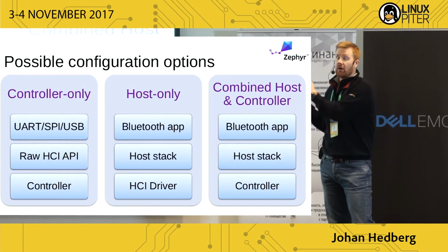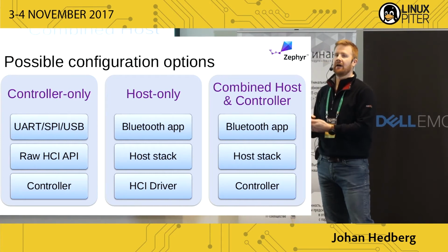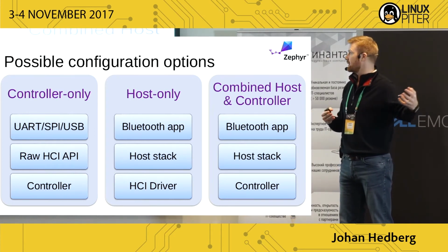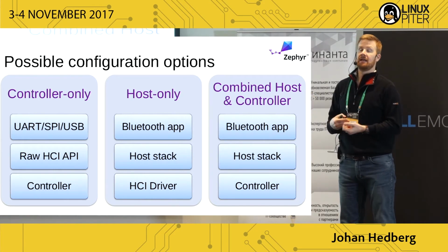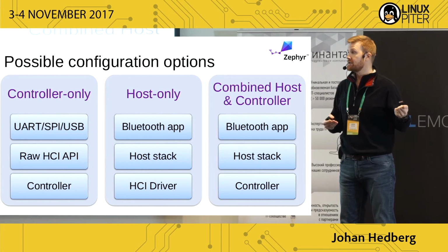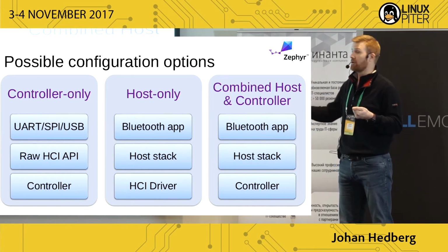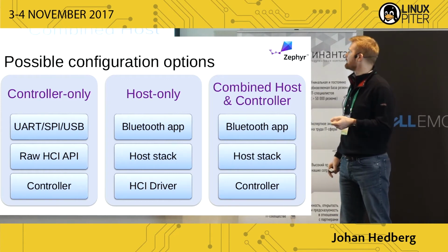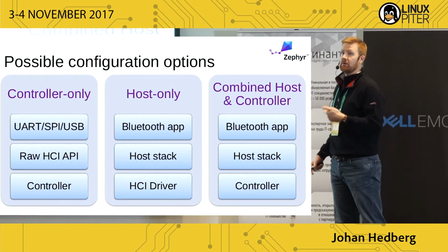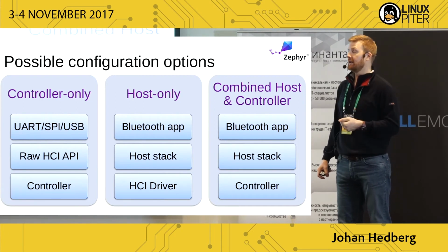The Zephyr Bluetooth stack, you can build only the host, in which case it requires an HCI driver for a physical HCI transport, like UART, for example, and then the controller will sit on another chip. An example of this is the Arduino 101, where you have the Quark running the Zephyr host stack, and then you have an nRF51 running the Zephyr controller, and they talk to each other over UART. And then, as I mentioned earlier, you can have them running in a single chip. So you could do this right now with any Nordic controller, the nRF51, and then they have the newer one, the nRF52.